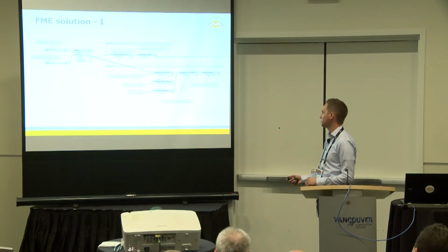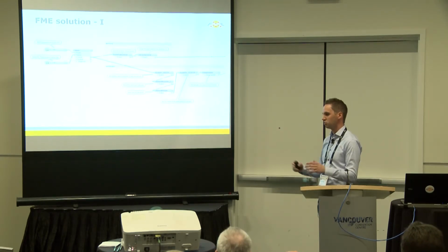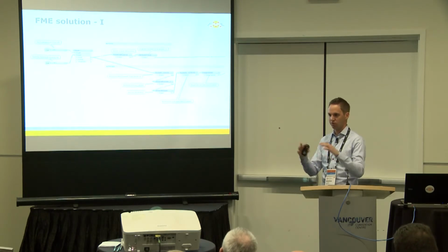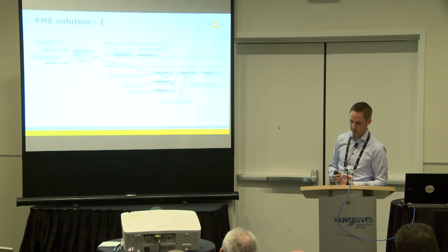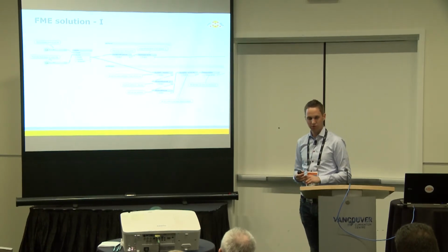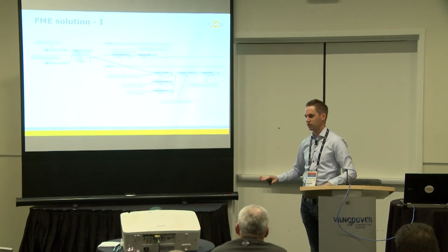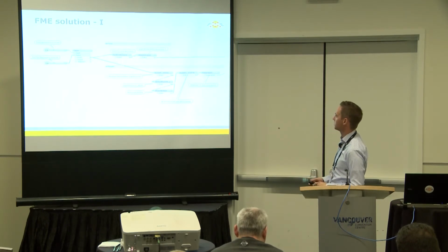So the FME workspace, first of all, I take the flood result and clip it with some type of a boundary. It could be that you have a very large flood model and you're only interested in a small area. Typically, we work for municipalities, and they are definitely not interested in water that's outside the municipality boundary. So we cut the boundary for the municipality.